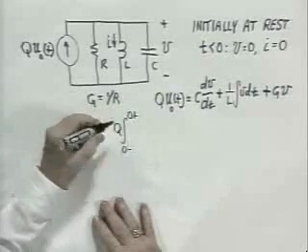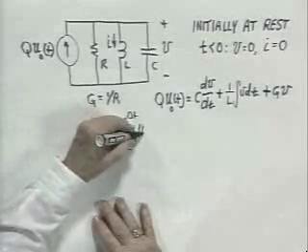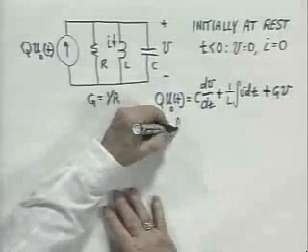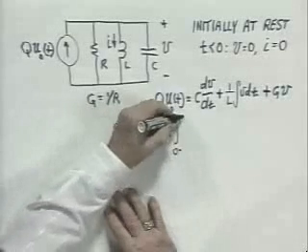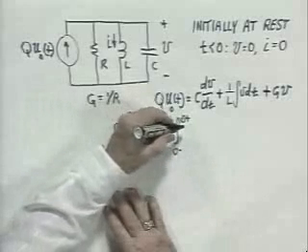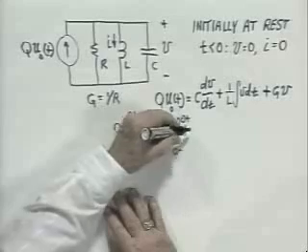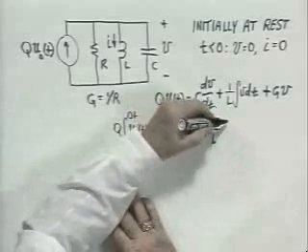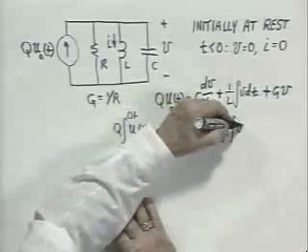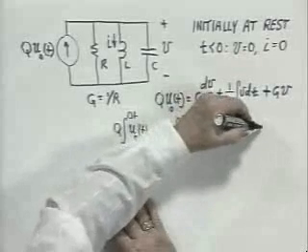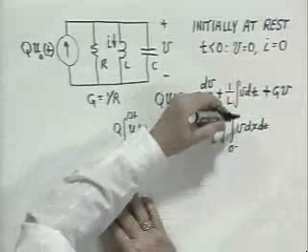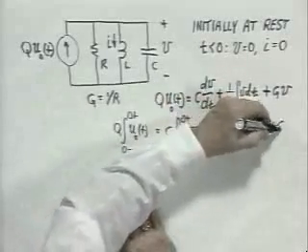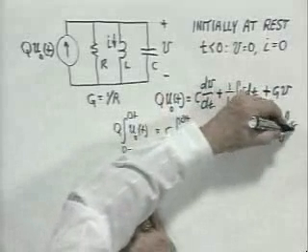I'll take the constant Q outside, u0(t) equals C times the integral from 0 minus to 0 plus of dV, plus 1/L times the double integral of V, with dummy variable, both from 0 minus to 0 plus, plus G times the integral of V dt.